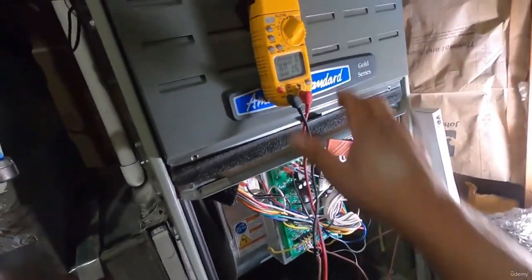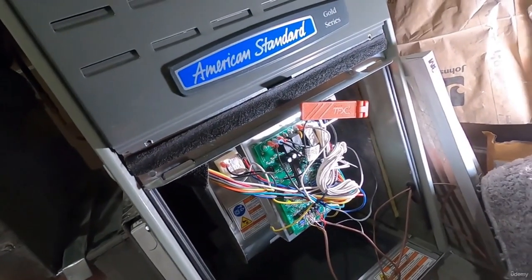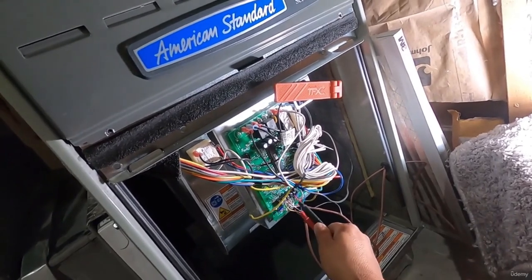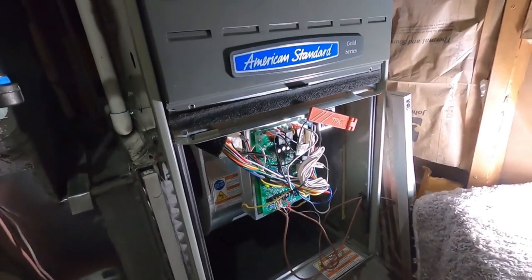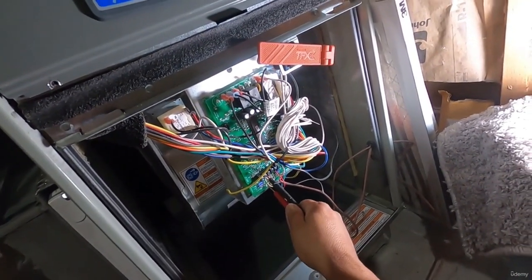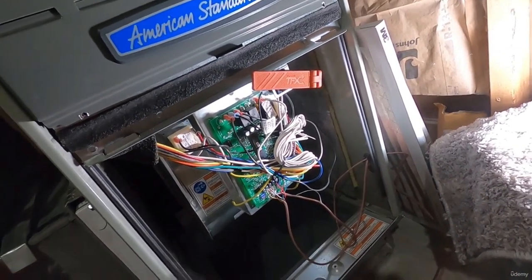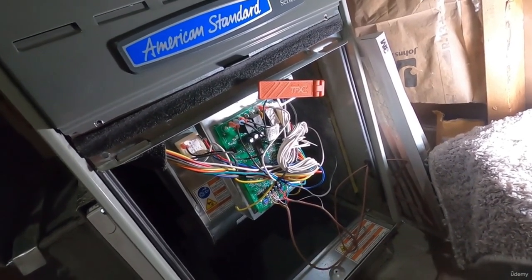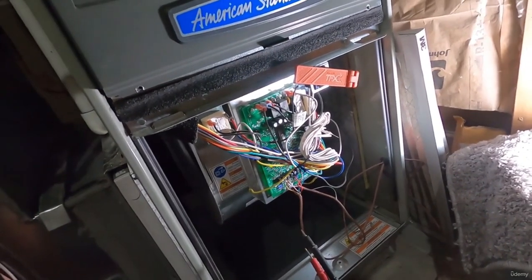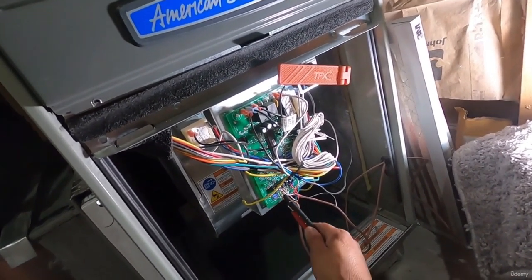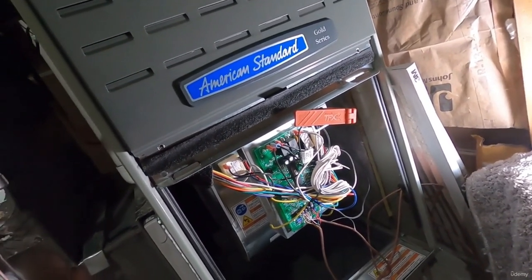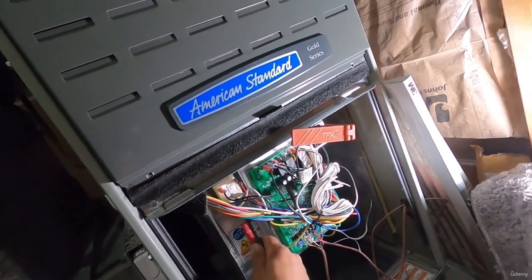Okay, so that's kind of how you test for voltages, making sure you're getting the voltage to the board, which is going to be at the R. The R sends it up to the thermostat. The thermostat sends it to the yellow, which comes back down and energizes the condenser outside. And if the condenser outside doesn't come on, we're going to troubleshoot that as well on the contactor. But here I want you to make sure that you just have 24 volts come down to the Y. If not, do these steps that I just talked about, and you can tell whether it's a thermostat problem.